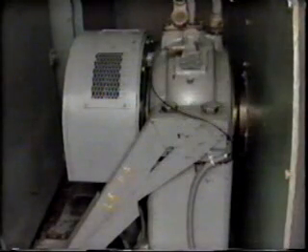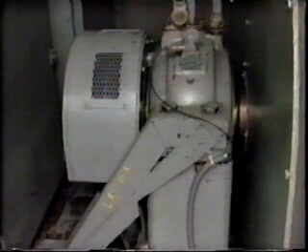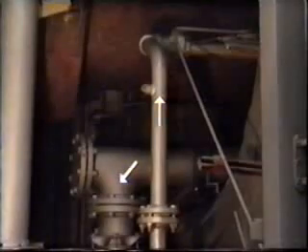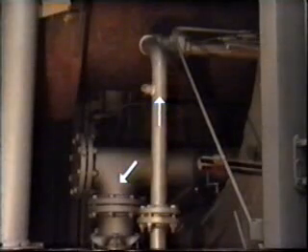The rotor is supported at each end by journal bearings. These must be very accurately aligned so as to maintain the same precise clearance between rotor and stator all the way along the length of the core. A forced lubrication system is required for the bearings.